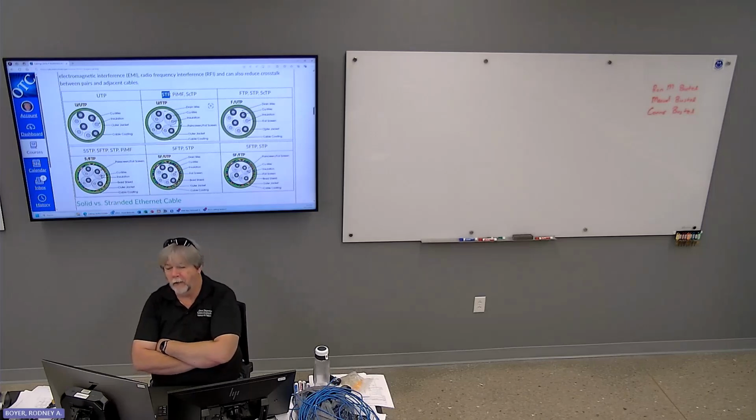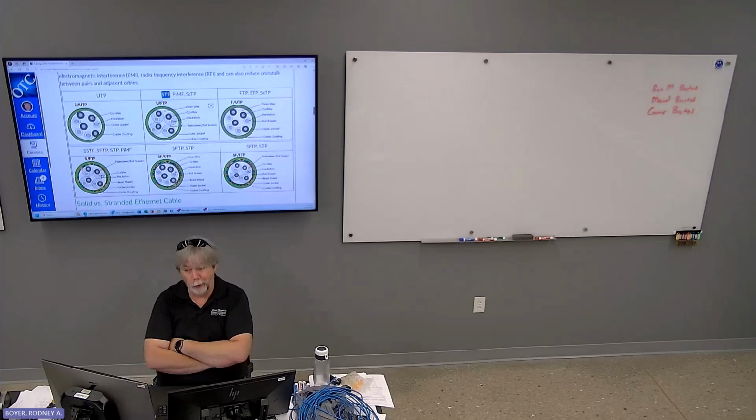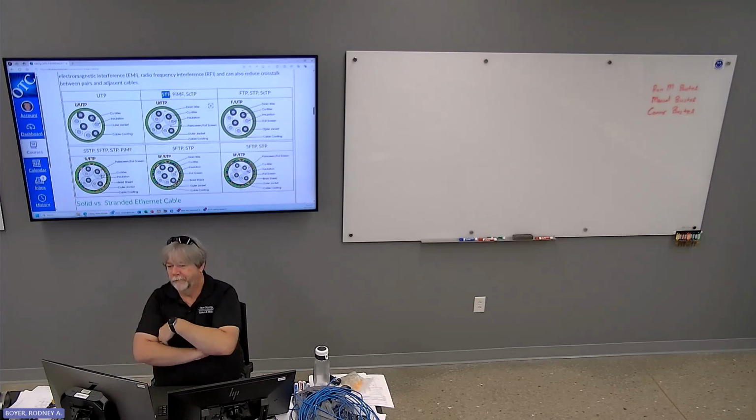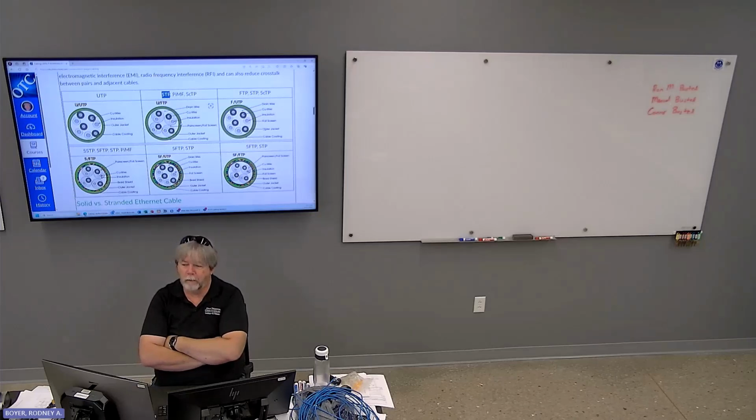Any motor that's being run off of a VFD is supposed to have VFD rated cable, which in itself is actually double shielded.